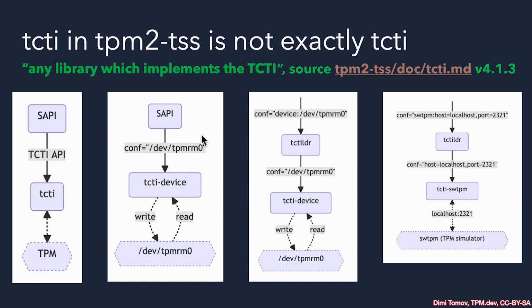Now, if we take it a step further, because TPM can be interfaced in multiple ways and there are multiple variants of TPMs, for ease of use, especially during development, prototyping and testing, it's very handy to have a TCTI loader. This is a component that loads different TCTI libraries, like TCTI device, for example, or the TCTI MSSIM or the TCTI SWTPM, depending on what simulator we're using, and it walks through the different TCTI libraries until it finds a working TPM.